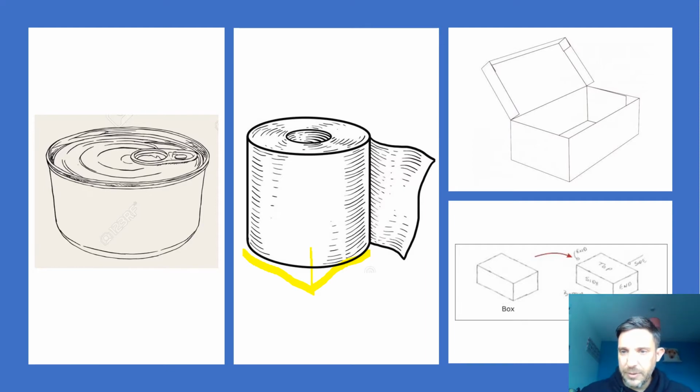And then over here with this box, again, this is much easier to draw because it's all straight lines. Once you've put your baseline in and you've projected vertical and you've projected 30 degrees and 30 degrees, it becomes very, very easy to draw.